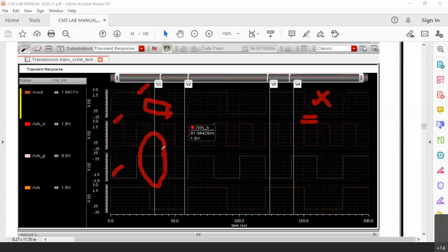For these complications, transmission gate has not yet become completely popular, even though it is saving power, there is no power consumption at all. Still, we cannot completely implement any design using only transmission gates because of these problems. That is why we have purposefully put that 1 picofarad capacitor, so that you will understand, in a no-load condition as well as in the loaded condition, what are all the complications as logic levels we are going to have while we implement transmission gates.